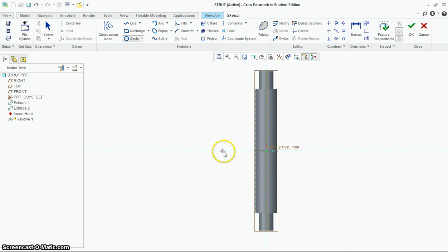centered with the rolling pin, and I'm going to have this circle open up and come slightly into my actual shape. Don't go all the way to the center, or that's going to lock in a constraint. Don't go to the edge, or that'll lock in a constraint. And then go ahead and middle click, and you're going to get a weak dimension here.